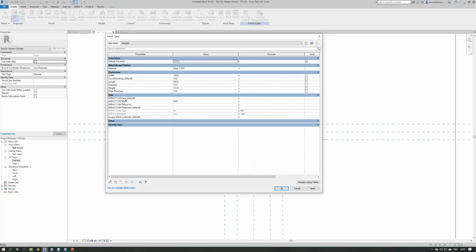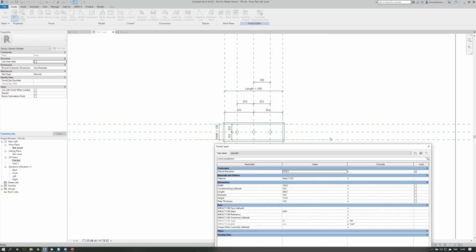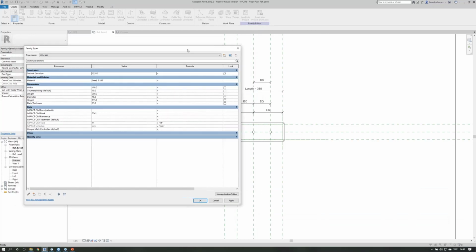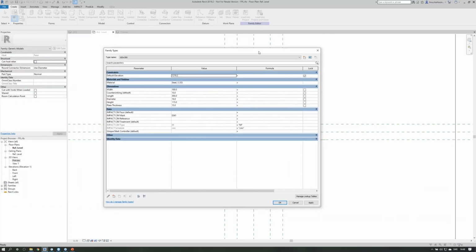We apply some parameters that are needed for the element to be saved in the database, and so we can use our Impact tools to actually apply the different custom materials in different ways. So I just wanted to show basically how to go from a family to actually draw the custom material, and it's pretty simple.